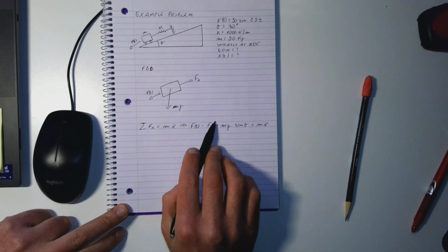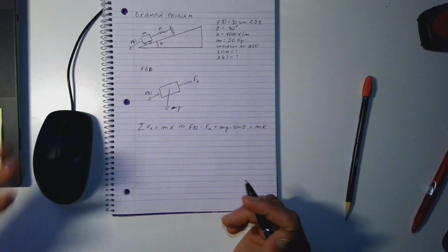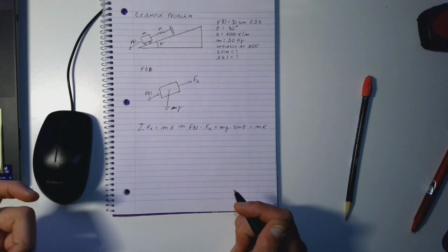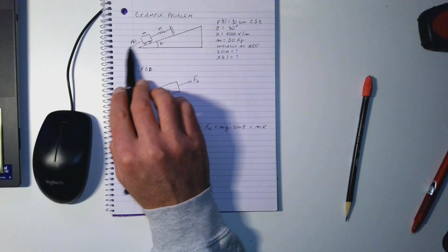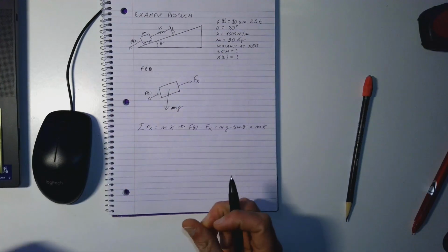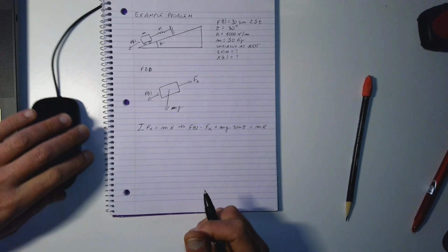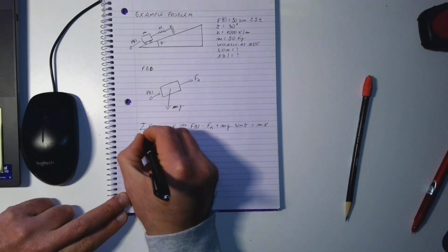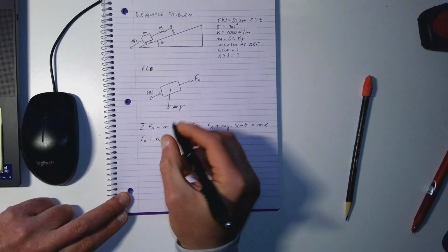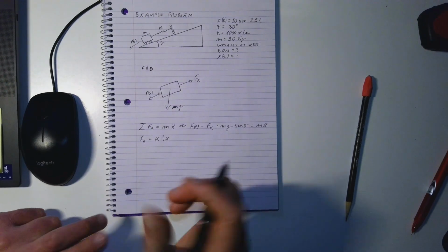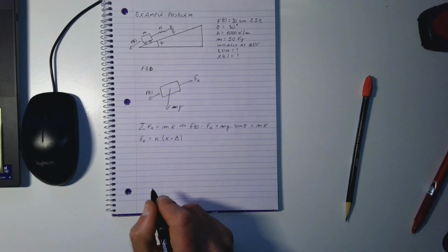Now we have to plug in the force of the spring. The force of the spring is the elastic constant multiplied by the displacement. Since we have the force of gravity extending the spring, we will have a static component and a dynamic component. So we can write the force of the spring as k times x, which is the changing displacement, plus delta, which is the static displacement.